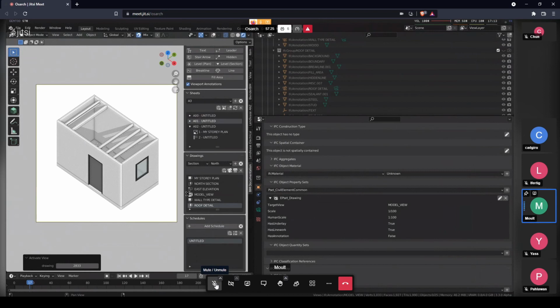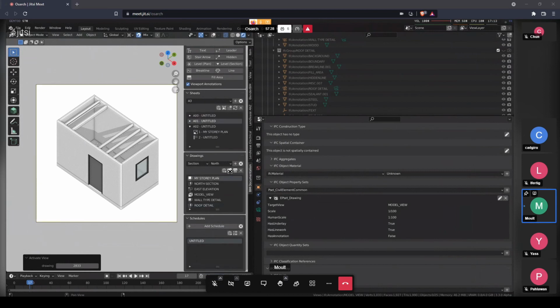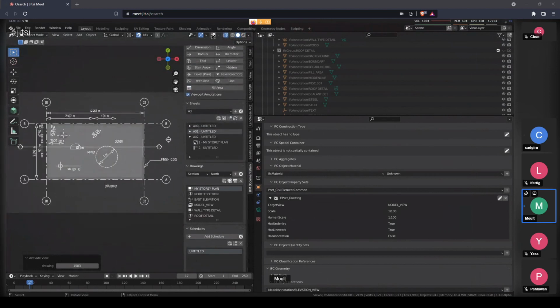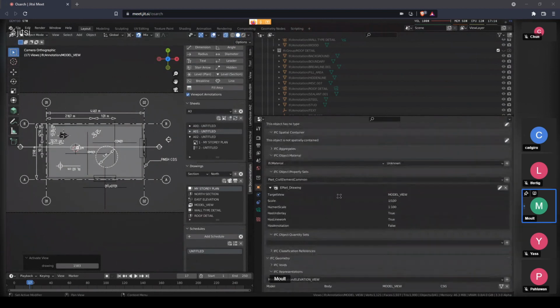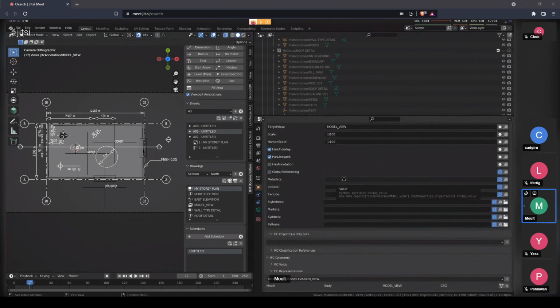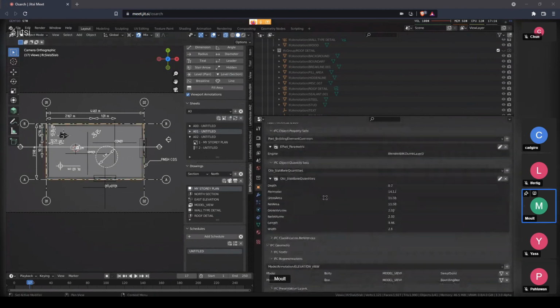Oh, I should mention a couple of other features. So let's go back to this view, and I'll turn on that line work so it's easier to see what these things are. Metadata means to include extra data into the model. So for example, let's say I want QTO slab base quantities depth to be a parameter inside my SVG.